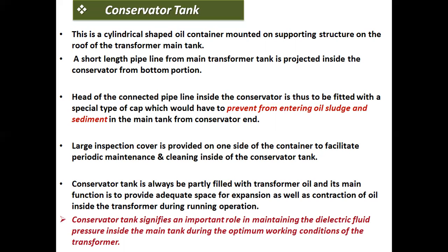A large inspection cover is provided on one side of the container to facilitate periodic maintenance and cleaning inside the conservator tank. The conservator tank is always partly filled with transformer oil, and its main function is to provide adequate space for expansion as well as contraction of oil inside the transformer during running operation.